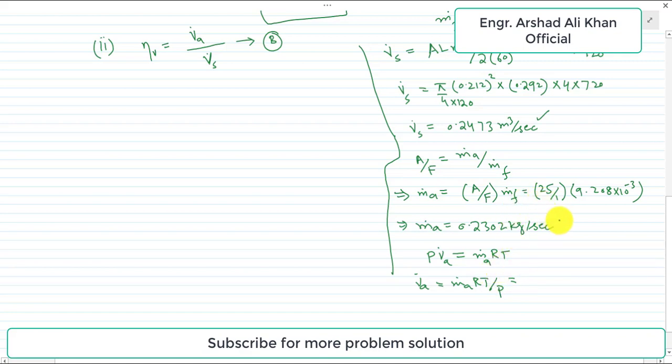M dot A is known to us. It is calculated over here: 0.2302 into the value of R for air, which is 287 joule per kilogram per Kelvin, and the value of T is given over here, 15 degrees centigrade or 288 Kelvin, divided by P. P is the pressure and it is 1.01 bar.